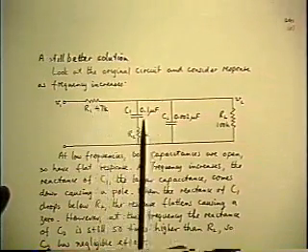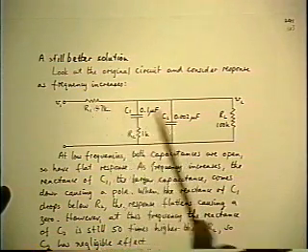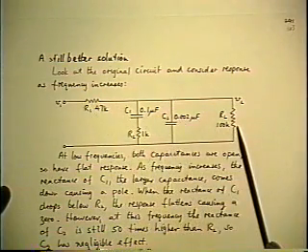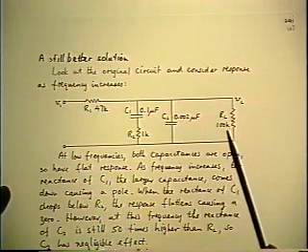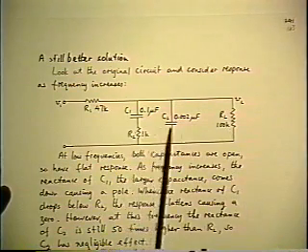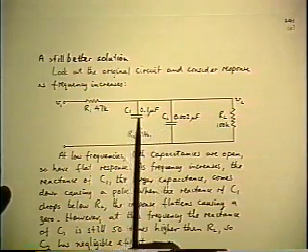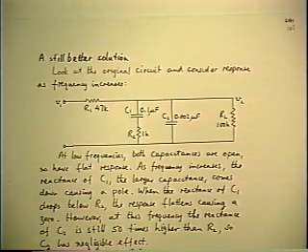What happens is, at 0 frequency, the two caps are open. So you have a simple resistive divider, so you can write down what the 0 frequency flat gain asymptote is. It's just that resistive divider. As frequency increases, the reactances of the two caps start to come down from infinity.